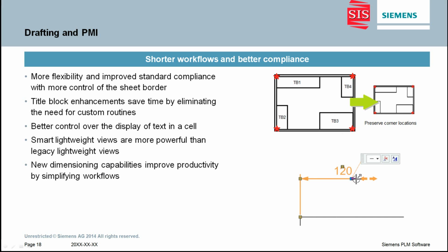Border and zone enhancements include greater control over the elements of a sheet border display. This includes line width and color controls, arrow display, triangular trimming marks, zones created from the center of a trim sheet, independent control over zone labels to skip, and additional standard-specific behaviors.